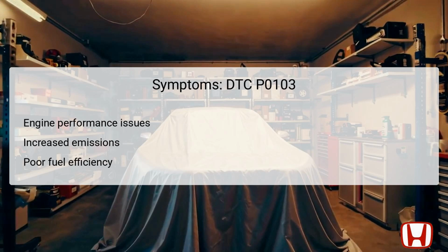Symptoms of the DTC P0103 can manifest as various engine performance issues. You may notice reduced power or acceleration, which indicates that the engine is not receiving the correct air-fuel mixture. Increased emissions could lead to potential failures in emissions tests, as the engine's combustion process is thrown off balance.